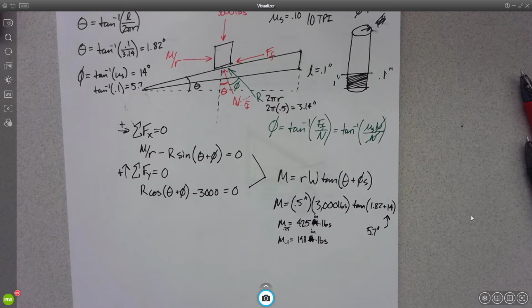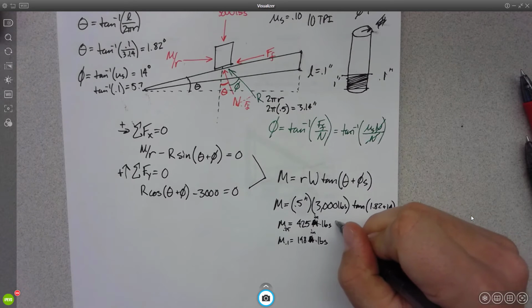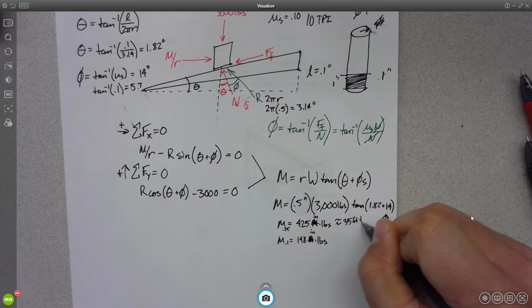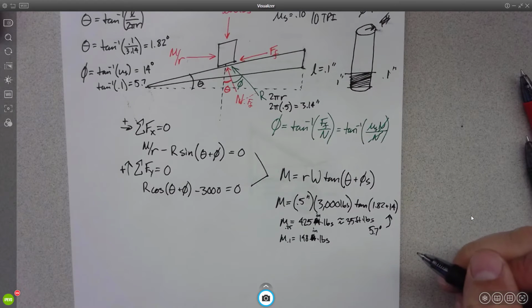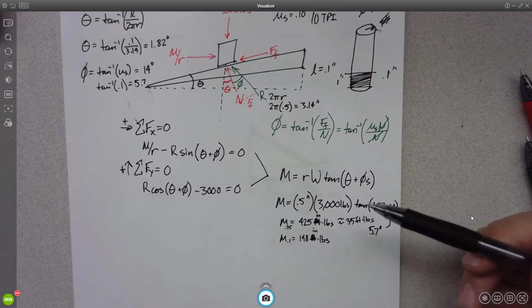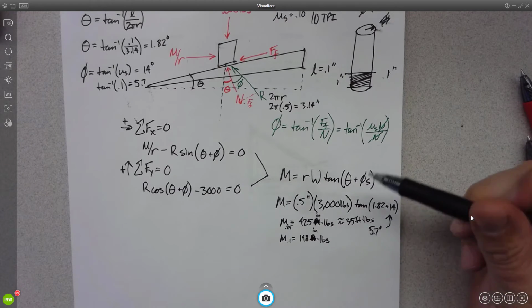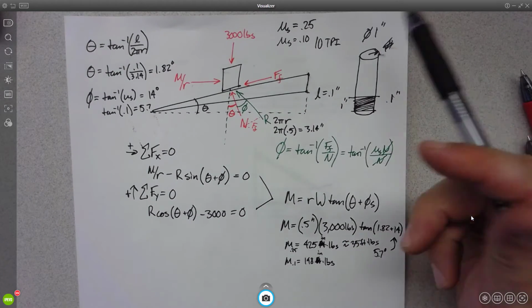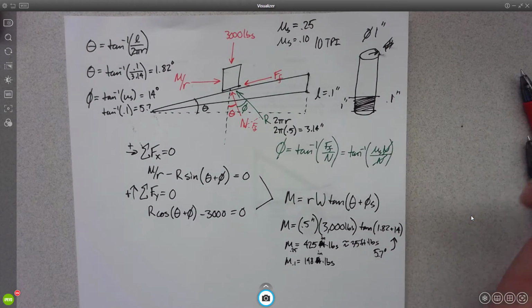That means 425 pounds at 1 inch, or 1 pound at 425 inches, but 425 inch pounds, let's divide that by 12. 35 foot-pounds. That I can do, right? I can put 35 pounds 1 foot away from this screw, right? I can lift my truck. Strong. 3,000 pounds, no problem. I'm a mechanical engineer. Ha! If it's good enough for the Egyptians to build pyramids, it's good enough for us, right? Okay?